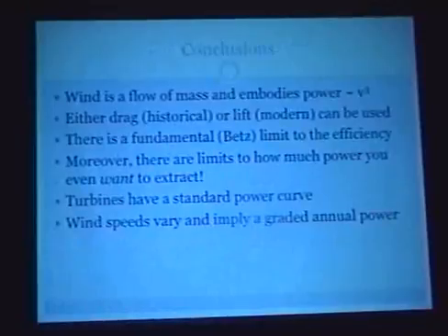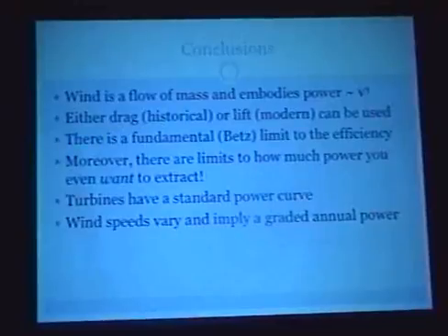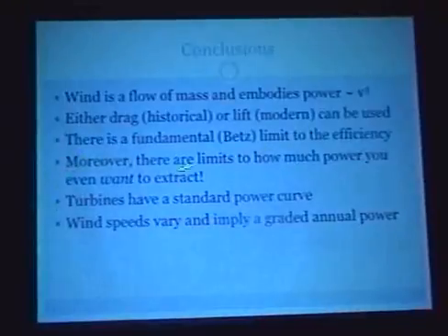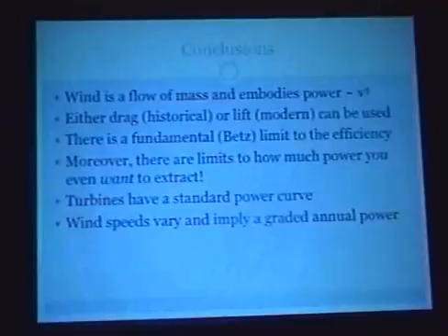So just to wrap up, the way to think about wind is it's a flow of mass, and it embodies some power that scales with the velocity cubed. And you can either use the drag force, which is what was used historically, a long time ago, or you can use lift, and that's much more the modern way. But any way you extract power from the wind, there's some fundamental limit to how efficiently you can extract that power, this Betz limit.